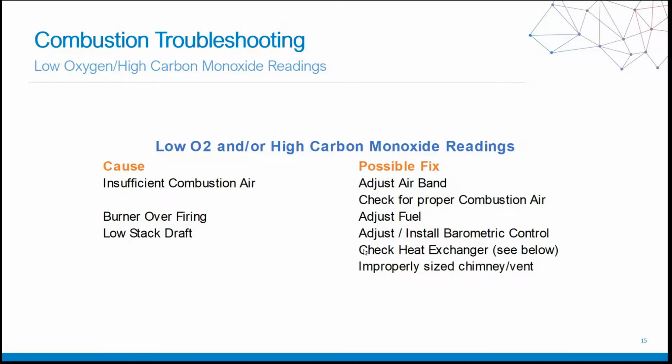And then also we have low stack draft. Do we have to adjust or install a barometric damper? Do we have an issue with our induced draft motor not allowing the flue gases to terminate properly and leave the system properly? Or do we have a cracked heat exchanger? Those are some of the things that we need to check for.